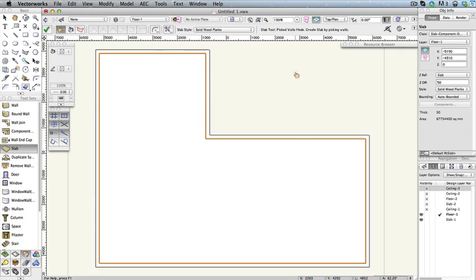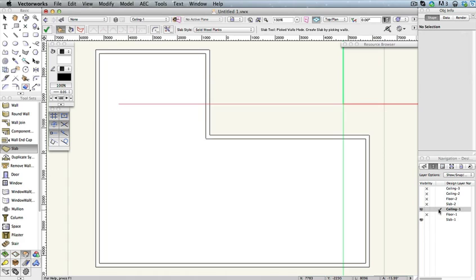In the navigation palette, set the design layer Floor 1 to Invisible and design layer Ceiling 1 to Visible. Also, make Ceiling 1 the active design layer. The reason why we kept design layer Slab 1 visible for the creation of the finished floor and ceiling is because this design layer contains the walls, which are the bounding objects for both the finished floor we just created and the ceiling we are about to create.